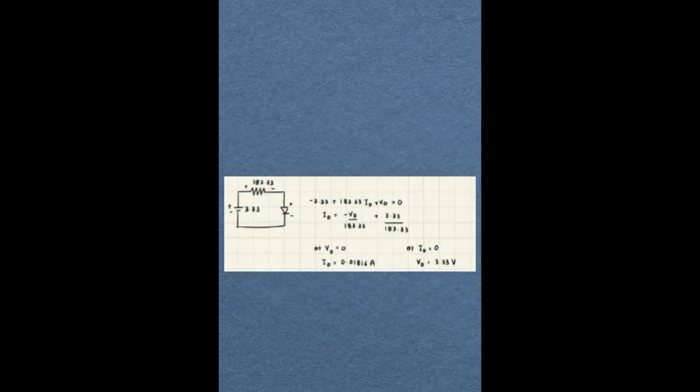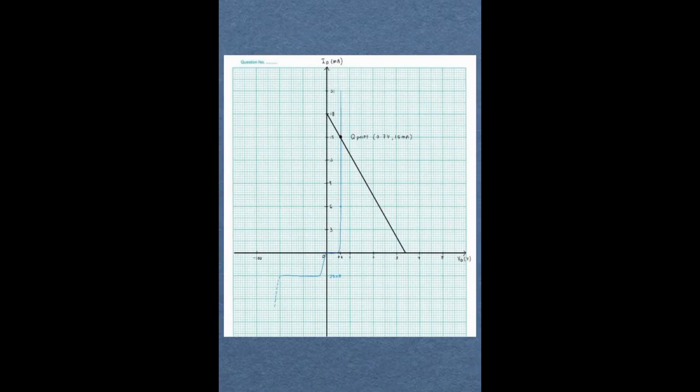From these values obtained, this is how the Thevenin circuit will look like. Onwards, we could apply KVL in order to find the maximum diode current and maximum diode voltage, where at maximum diode current, the voltage will be at 0 and vice versa. When these values were plotted, it will result in what we called a load line. Now we are closer to the end. The only remaining thing we need to do here is to plot the load line on the same graph as the IV characteristic curve of diode to find the operating point. By the way, we just perform a graphical analysis here.